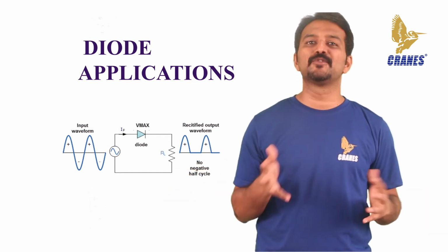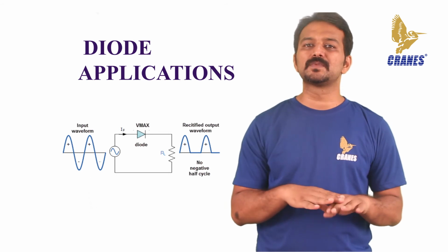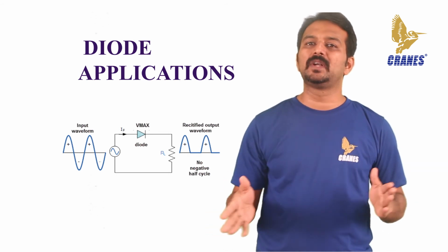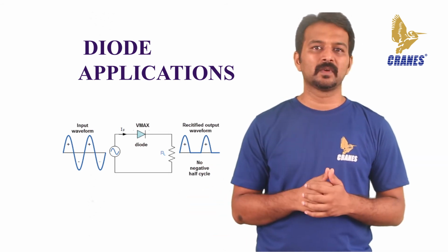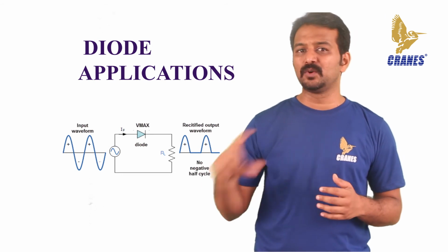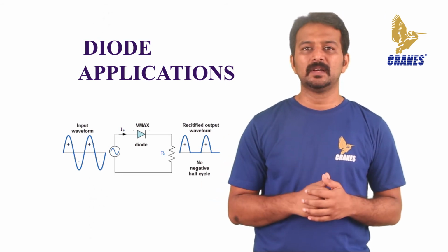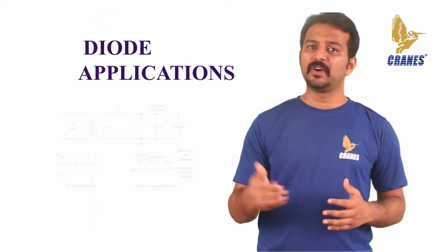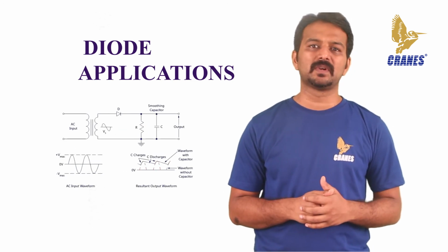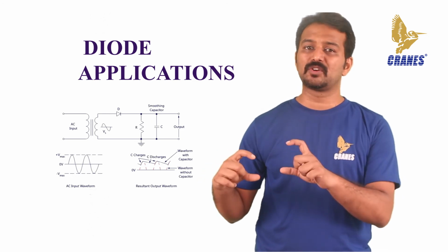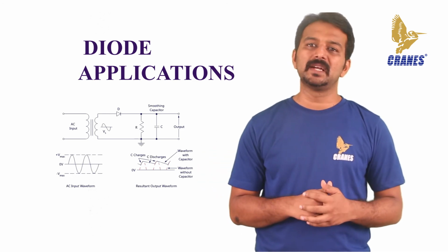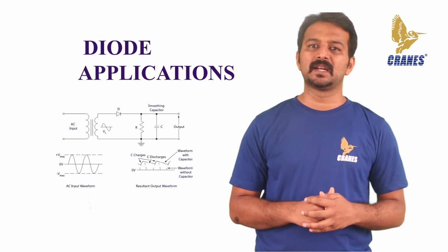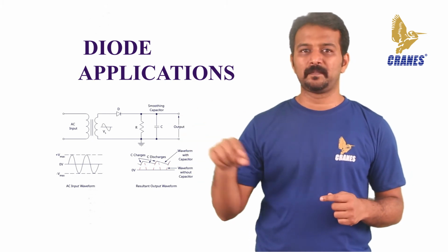Hence, no current flows through the load. The circuit becomes an open circuit. No voltage appears across the load. Both the voltage and the current at the load side are of the same polarity, which means the output voltage is pulsating DC. Very often this rectification circuit has a capacitor connected across the load to produce a steady and continuous DC current without any ripples.